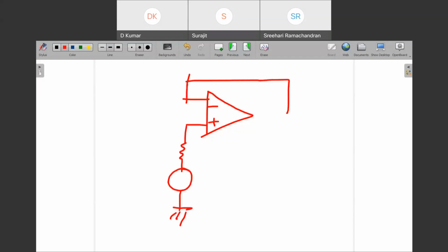So is any delay created when the buffer is connected to a circuit? Yes, when any buffer is connected there is a delay. It happens in digital circuits. Here it is analog, so definitely there will be some drop and everything, but delay we do not consider in analog. Delay happens when there is some capacitance, some time constant. Right now we are not considering any capacitance.